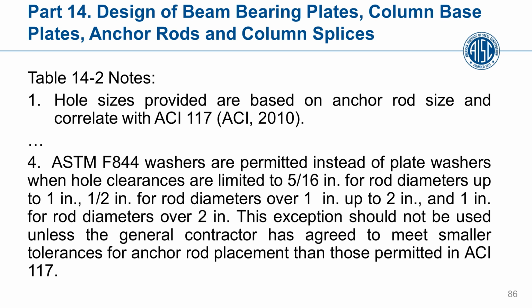One other change, ASTM F844 washers are permitted instead of plate washers when the hole clearances are limited to 5/16 inch for rod diameters up to 1 inch, 1/2 inch for rod diameters over 1 inch and up to 2, and 1 inch for rod diameters over 2 inches. Now, what you have to realize is that it was always expensive to make plate washers. If you can use a standard off-the-shelf washer, an F844 washer, it is also always less expensive and will reduce costs on your projects. So there's an advantage to allowing people to use a standard washer rather than requiring everybody to use a plate washer.